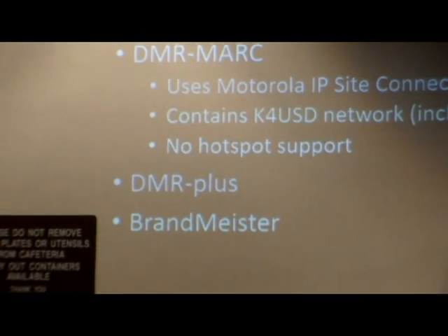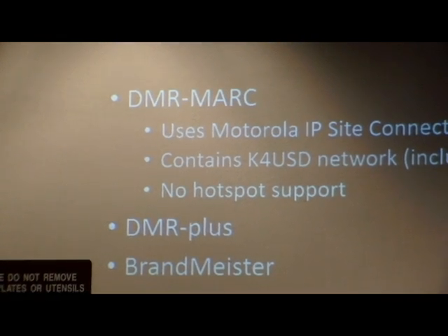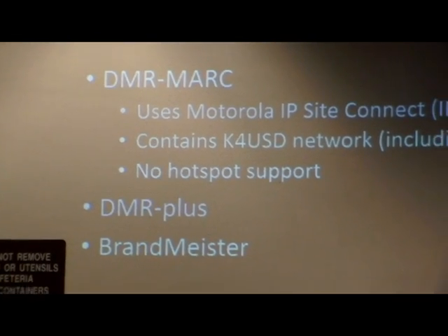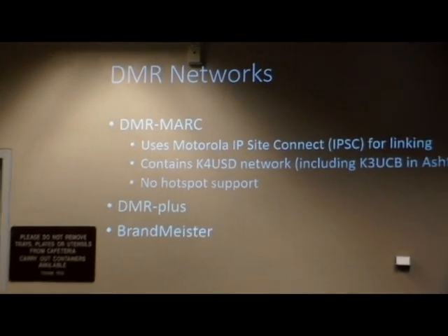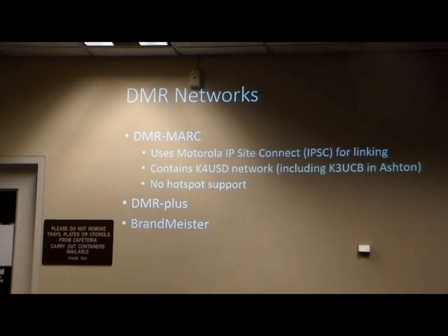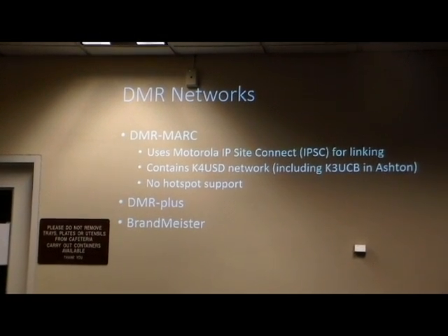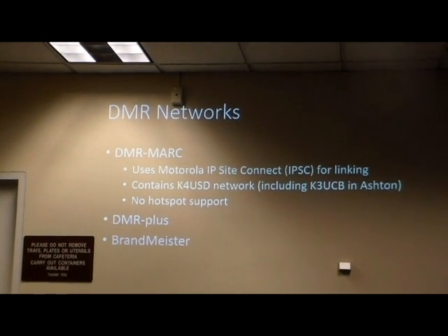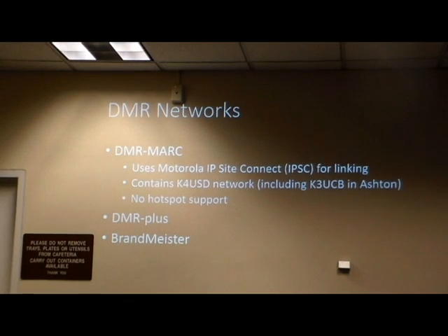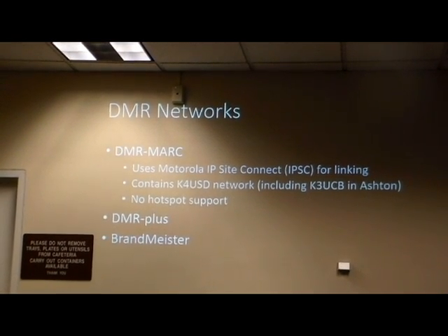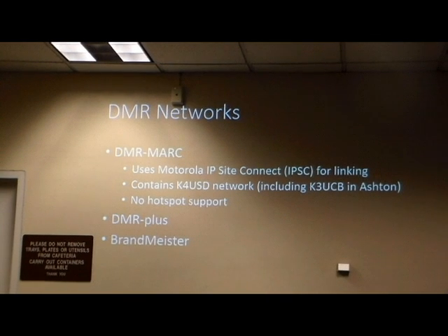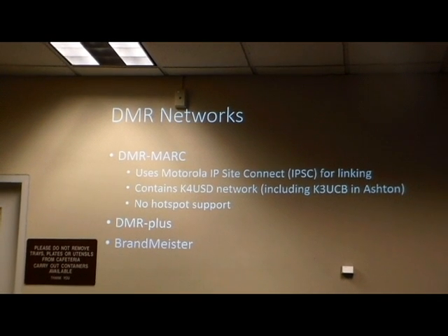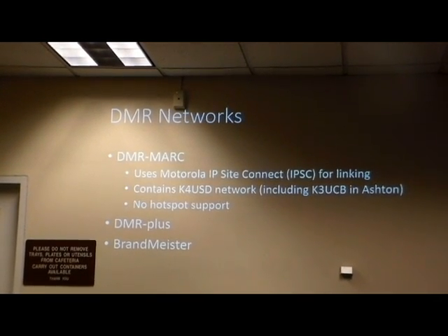DMR Mark tends to be very conservative. They are insistent on using only Motorola equipment, and they're very tied to a lot of those proprietary standards. Brandmeister has a lot of their own software stack, where they have implemented different protocols from different vendors. So you can have a really good mix of repeaters. You may find one guy on a Motorola repeater, another on a different repeater, and one guy on a hotspot that he's running off a Raspberry Pi. They support a lot of homebrew efforts. They provide the configurations, and anyone can join.